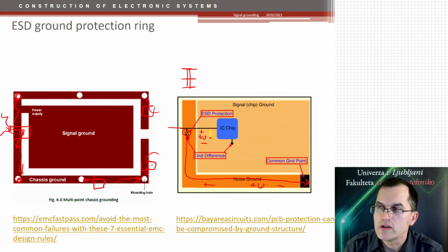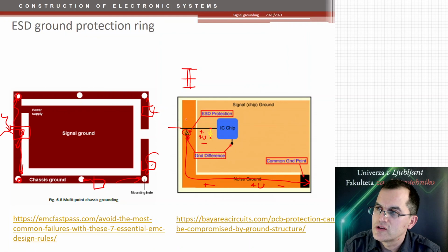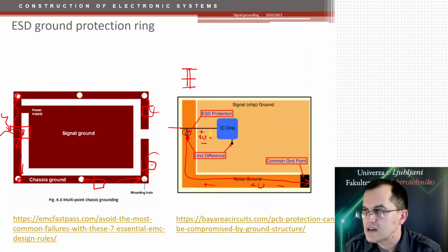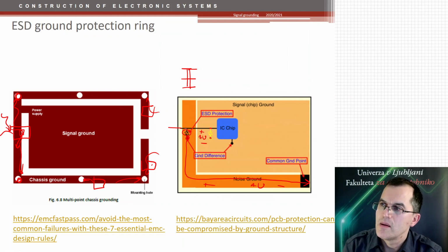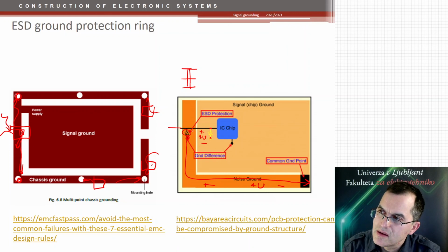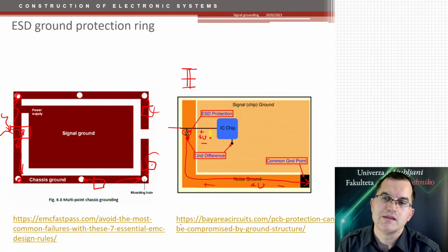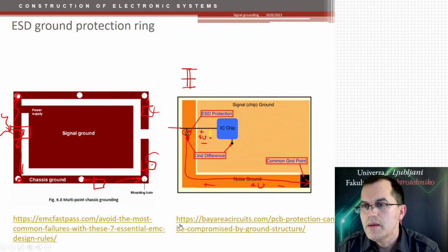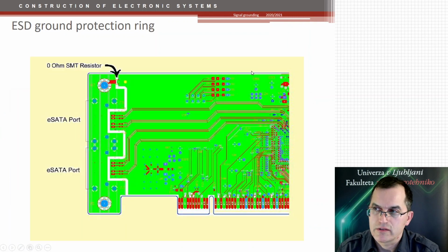So you want to provide a really low impedance protection ring so that the current pulses that are drawn by this and conducting through this protection ring should provide the lowest possible voltage differences. But it's still better than current that runs directly through the whole PCB. But in doing all that, you still can have a lot of problems.